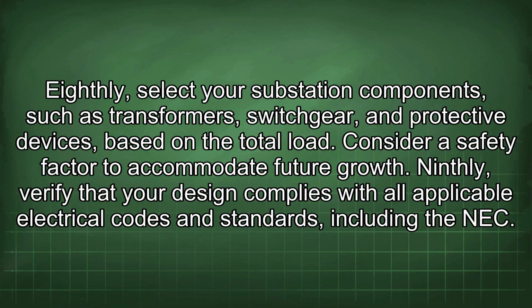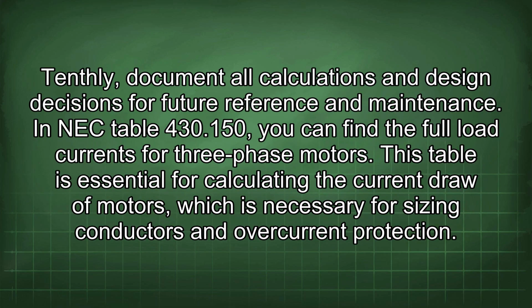Eighthly, select your substation components, such as transformers, switchgear, and protective devices, based on the total load. Consider a safety factor to accommodate future growth. Ninthly, verify that your design complies with all applicable electrical codes and standards, including the NEC. Tenthly, document all calculations and design decisions for future reference and maintenance.